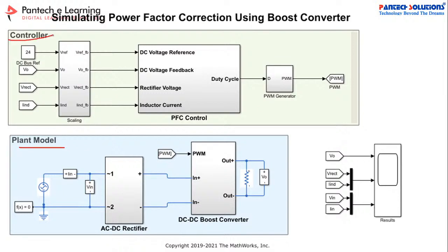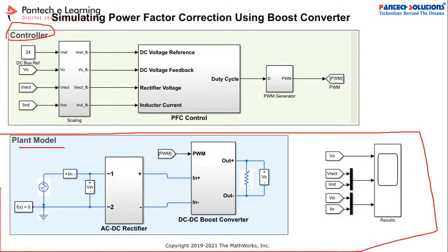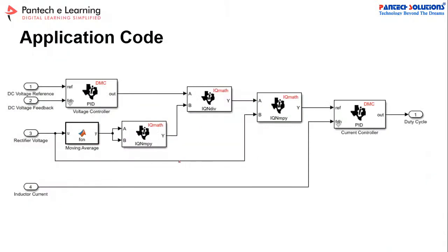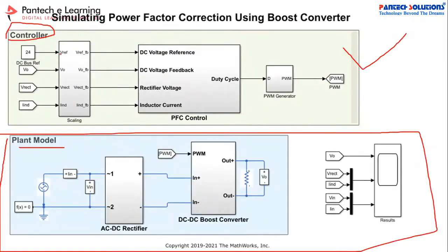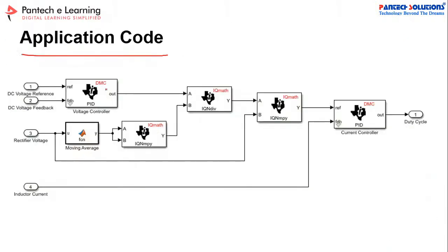Now you have to remove this model from the solutions, and you can take this controller alone. From this file, you can incorporate it into any one microcontroller. This is called application code, with the same logic like scaling or functioning, whatever it is. You have to convert this controller into microcontroller code. Inside the microcontroller, there are a lot of libraries.